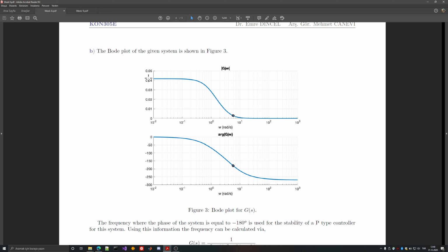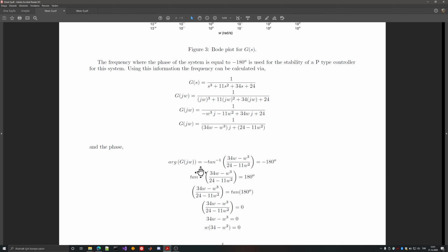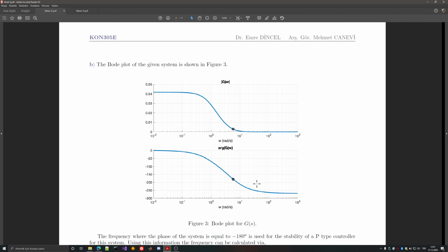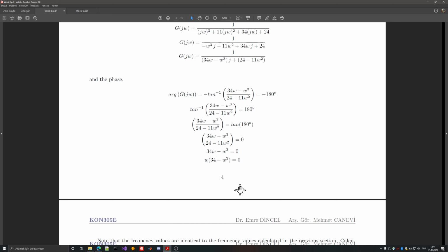So approximately 0.04. The inverse should give you something around 24. So basically, the second one of the critical points passes through minus 180 degrees. The other one, the negative root locus part, or the negative bound for the controller, should pass through 0 degrees.